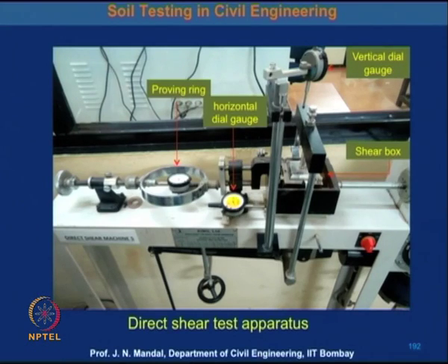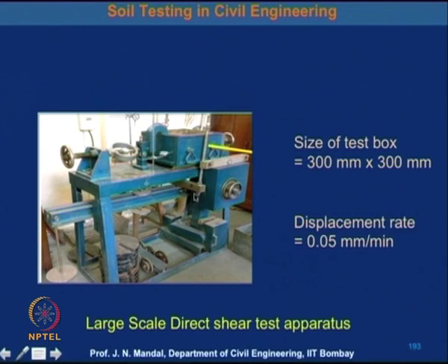Next is the large scale direct shear box test. Sometimes for some materials you cannot determine the direct shear strength from the small scale shear box test, which is 60 centimeter by 60, so you require the large scale direct shear test.